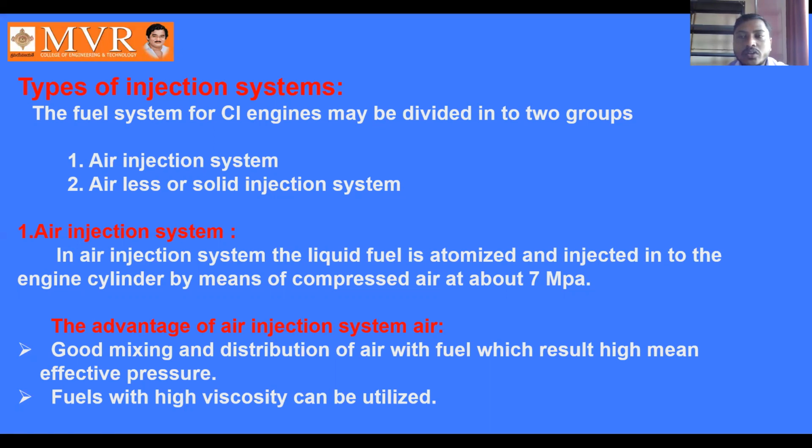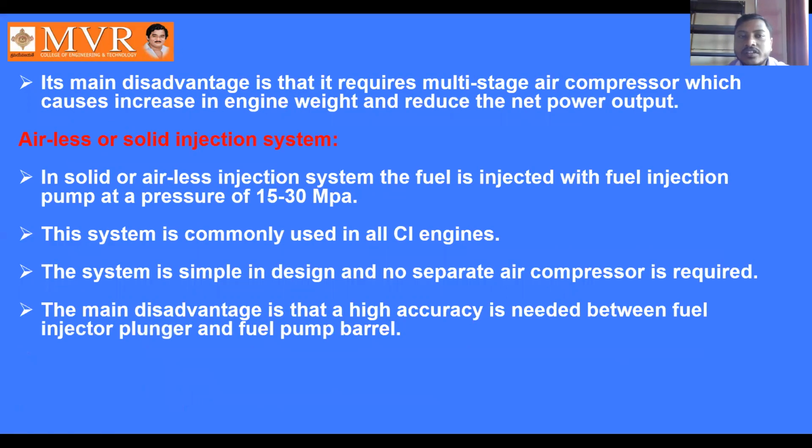Good mixing means both the air and fuel should be mixed and distributed in the engine cylinder to get a high mean effective pressure. Fuels with a high viscosity can be utilized for this air injection system. Its main disadvantage is that it requires a multi-stage air compressor.